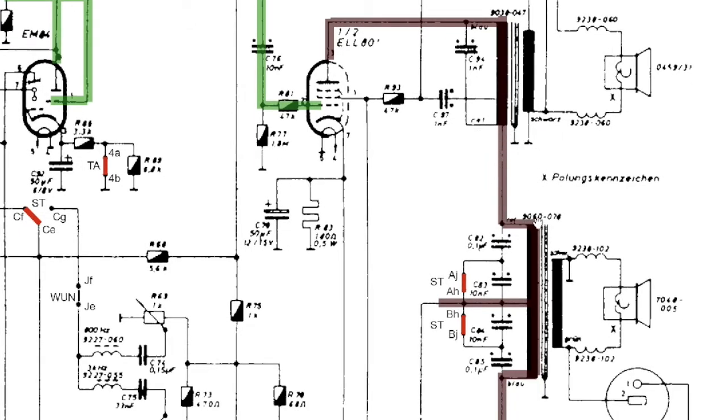Well, this path, the high frequencies don't really see this transformer. They see this capacitor. The DC connection to that transformer and that anode still goes through, because effectively at DC, this primary is basically an inductor. It just reduces the ripple. So DC is feeding that anode plate, but as far as the audio is concerned, it doesn't see this. So the only load that the mid to high frequencies have on this pentode, on this driver, is this transformer, and therefore that speaker produces that sound.